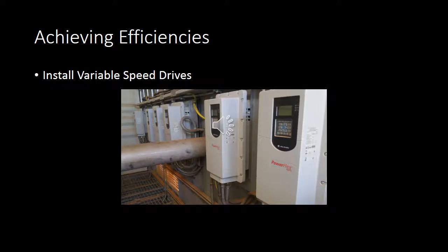Install variable speed drives. When there are strong variations in load and/or ambient temperatures, there will be large swings in compressor load and efficiency. In those cases, installing a VSD may result in attractive payback periods.